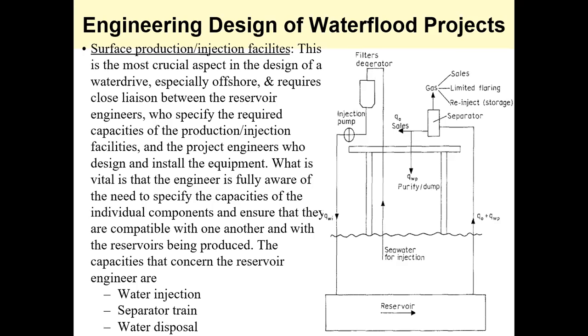What is vital is that the reservoir engineer is fully aware of the need to specify capacities for the individual components and ensure they are compatible with one another and with the reservoir being produced. So you need to specify the water injection capacity, separation train capacity, and water disposal capacity.